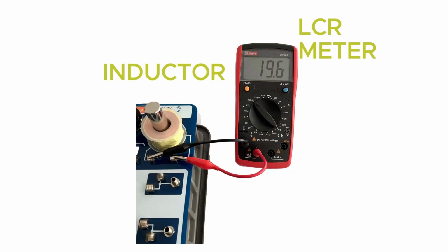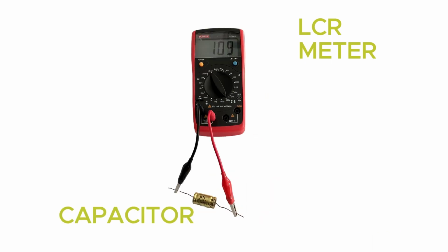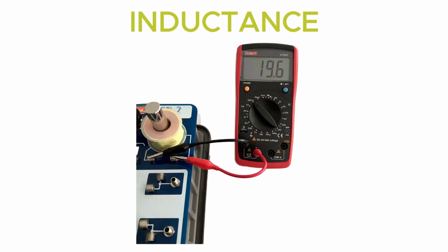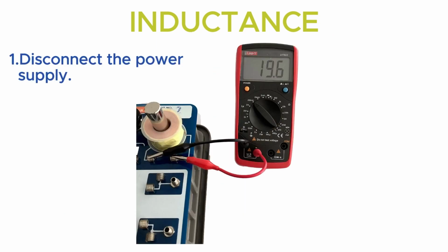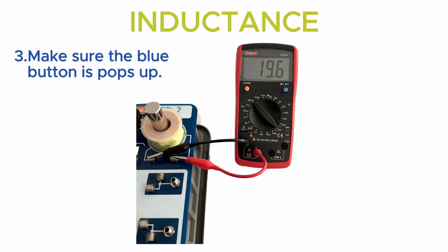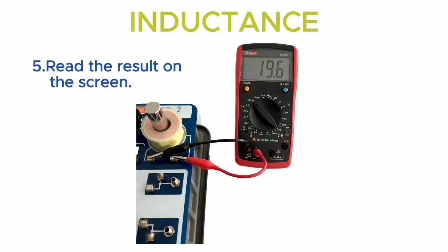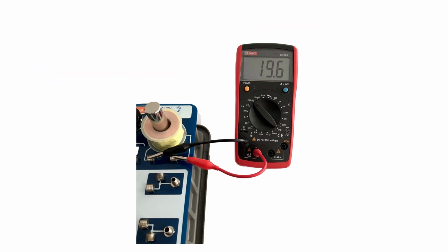Measure the value of inductance, resistance and capacitance using an LCR meter and record the values as in Table 2.1. To use the LCR meter for measuring inductance: 1. Disconnect the power supply. 2. Connect the red probe to the plus slot and the black probe to the dash slot, as shown in Figure 12.1. 3. Make sure the blue button pops up. 4. Turn the knob to the LX scale. 5. Read the result on the screen.